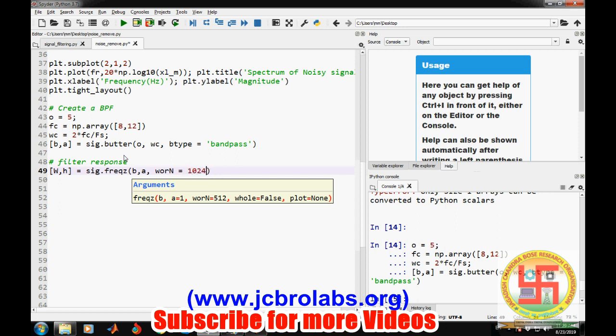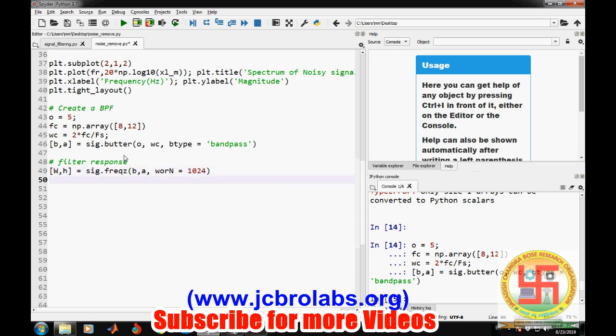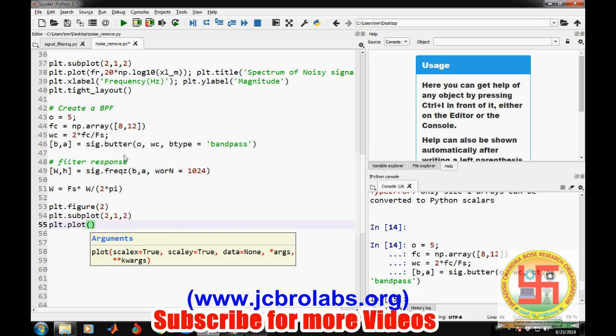So let's say 1024 number of samples, and then let's convert this w into frequency in hertz, because it is in the normalized domain in radian per second, so we need to convert it into hertz. W divided by 2 pi, and now we can plot it. So plt.figure 2, and then plt.subplot 2, 1, 2, and then again plt.plot this w comma 20 log 10, and that is h.